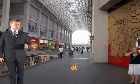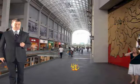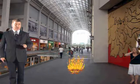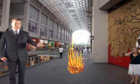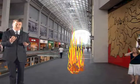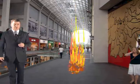Recent cases of poor design that have been witnessed include situations where natural ventilators have been hinged at the top so that they do not present anywhere near the required aerodynamic free area ventilation. In other words, they haven't got the right AV factor, they've not got the right area ventilation. There have also been situations where the spill plumes anticipated by the design fire engineers bear no resemblance to the actual spill plumes that would occur in the event of a fire. They've got too low a fire size. They might have thought, well, I'll go for a 2 megawatt fire, and it has actually been found to be a 5 megawatt fire, so the system won't work.